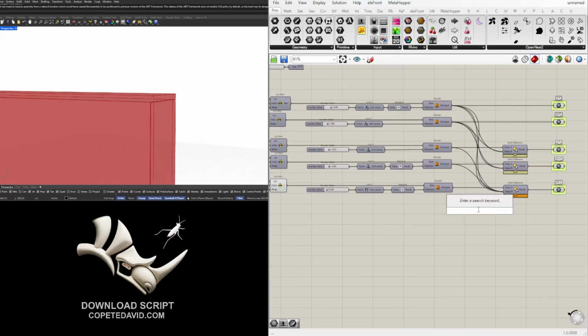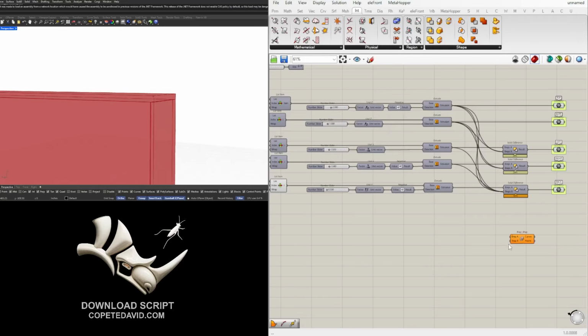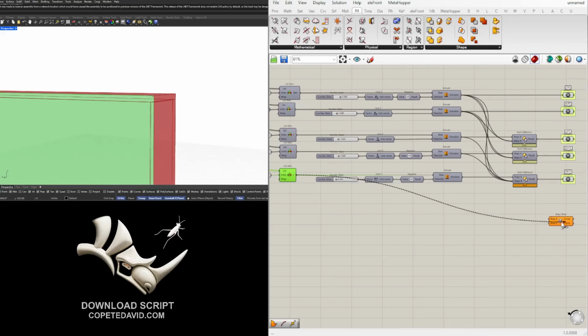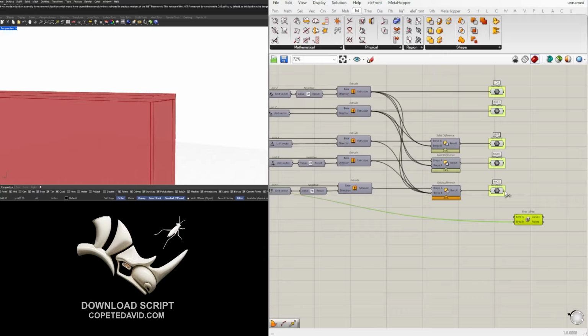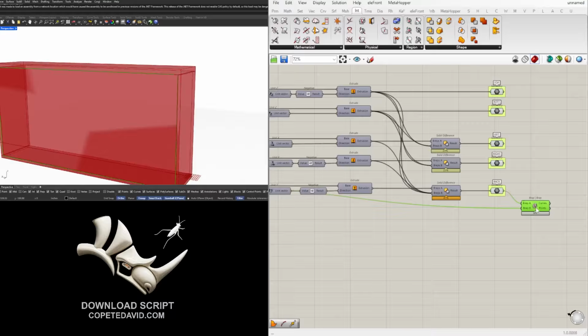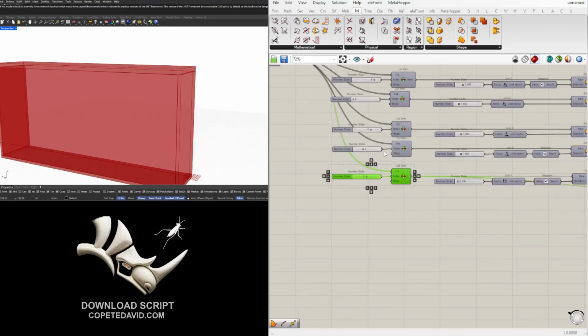So we'll go here to intersection, physical, brep with brep, and we're going to extract a curve where this brep B and this back brep A intersect. And notice that now we have a polyline at that location. So now we can hide this one.